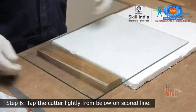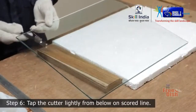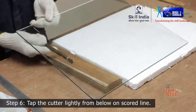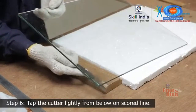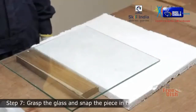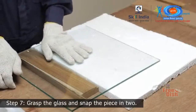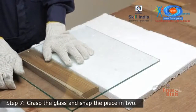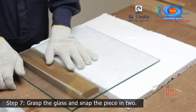Step 6. Run the cutter smoothly from one edge to the other. Ensure the scored line runs completely from one edge to the other. Step 7. After you've scored, go right ahead and snap the piece into two. Grasp the glass from each side of the scored line and snap the glass. Do not apply too much pressure.